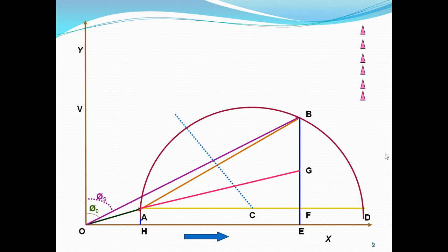Convert this Is to normal voltage level, that is Isn. So Isn is equal to Is into V1 by Vs. What is Isn?